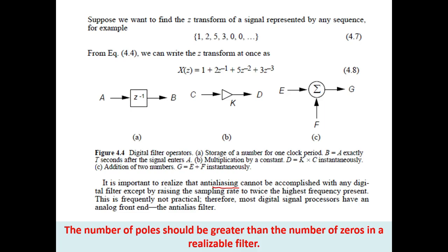So again, coming back to the lecture, in aliasing they will be mixed due to some reason. There will be mixing of the low frequency component and the high frequency component, right? Whether you do not fulfill this Nyquist criterion, or due to the non-ideality of the behavior of your device, due to that you will have aliasing. Okay. Now this process of anti-aliasing, that means removing the aliasing, cannot be implemented in any digital filter.